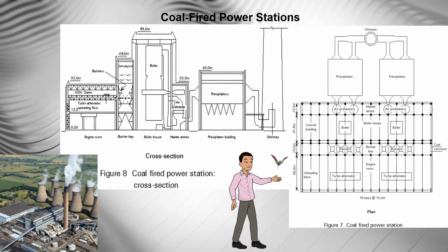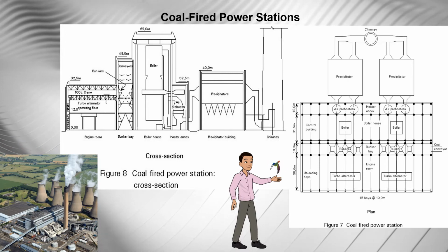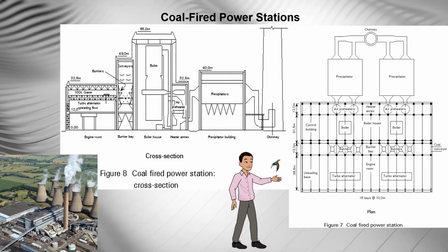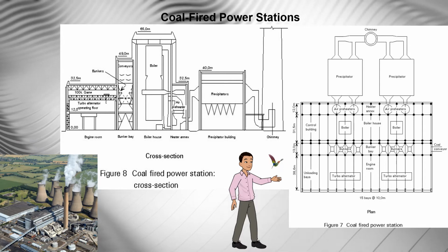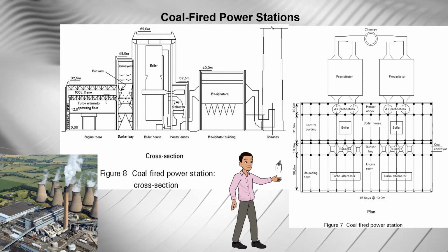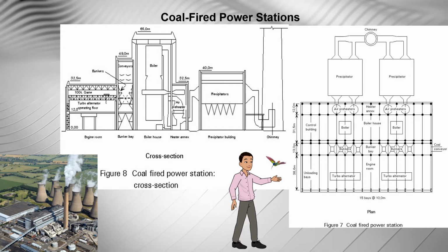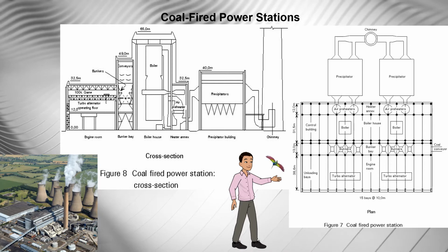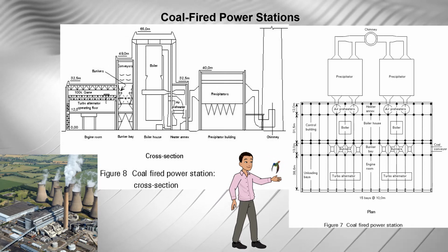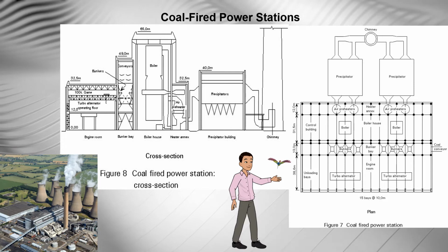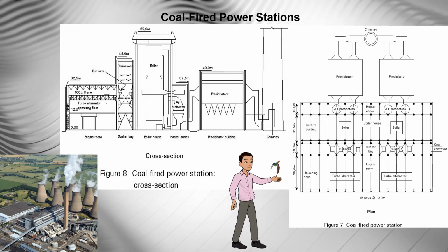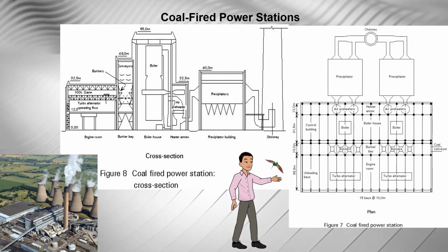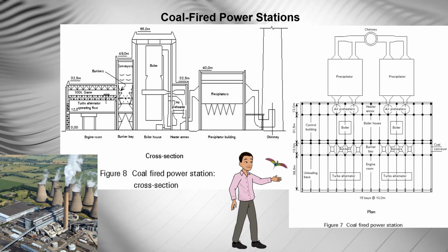In the bunker bay, which is also a steel structure, are large feed bunkers of 600 tons capacity constructed of steel plates, supported at high level, to which fuel is supplied by conveyors. There is a fire and explosion hazard in the feed conveyors and the ductwork connecting the bunker to the fuel mill and the latter to the boiler. Sprinkler and carbon dioxide fire protection is therefore required in this part of the plant, and fire protection is also applied to the steelwork.